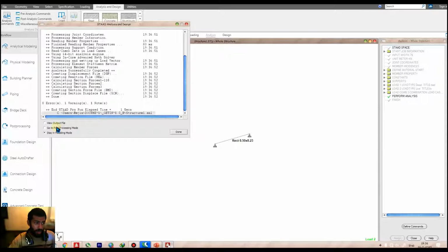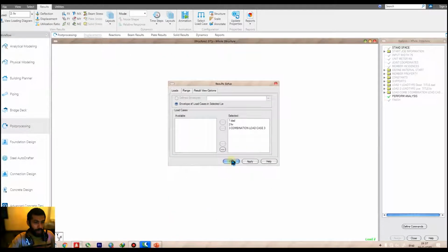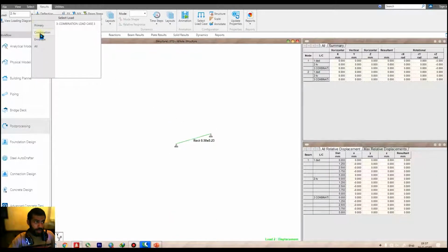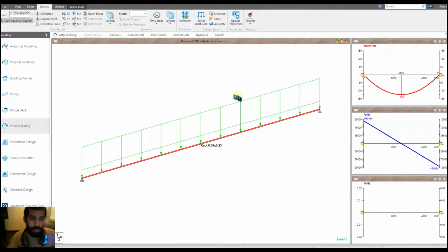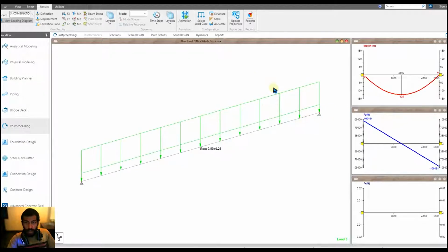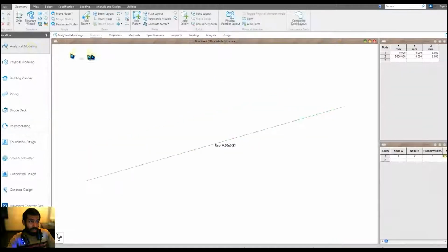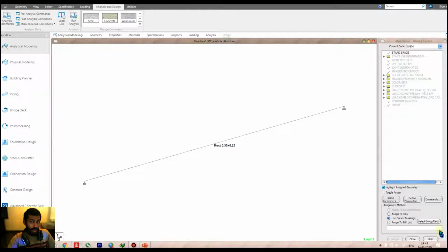Okay, what you're supposed to do is view the bending moment, get into post-processing mode, and first get into combination here. And so we are having the moment as 125, so that's a simple way of equating moments. After that, let's try to get into the design. So here is the design. We are going to design a concrete structure.